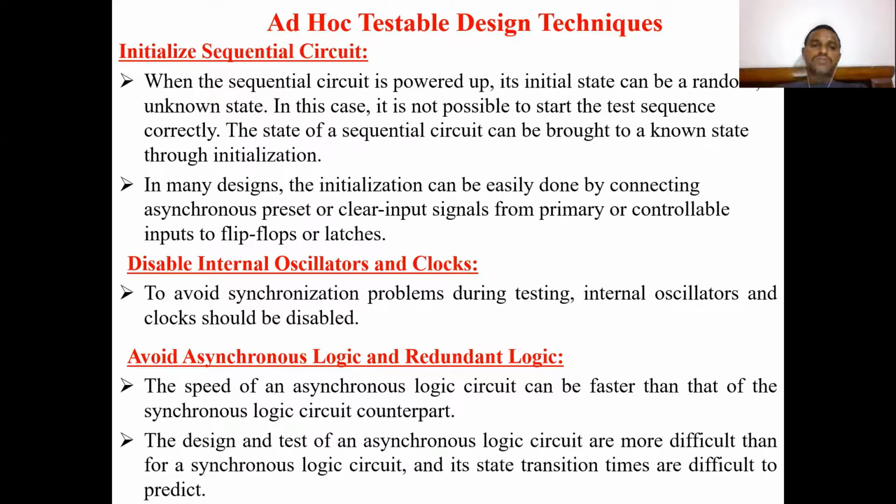The basic memory elements we will consider are flip-flops or latches. Any flip-flop has its own state. So how can you initialize sequential circuits before applying the test vectors? In many designs, the initialization can be easily done by connecting asynchronous preset or clear input signals from the primary or controllable inputs to the flip-flops or latches. That is how we initialize the sequential circuit.